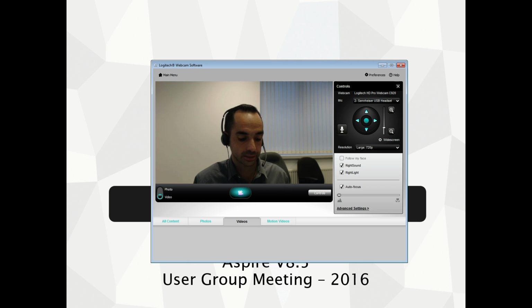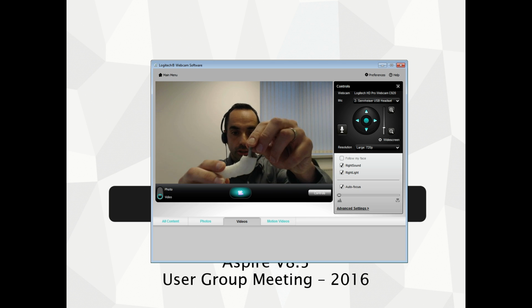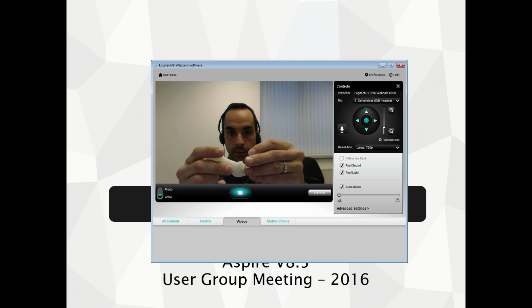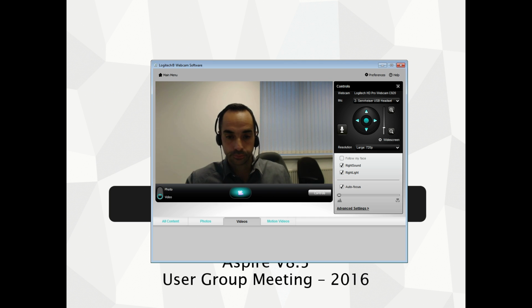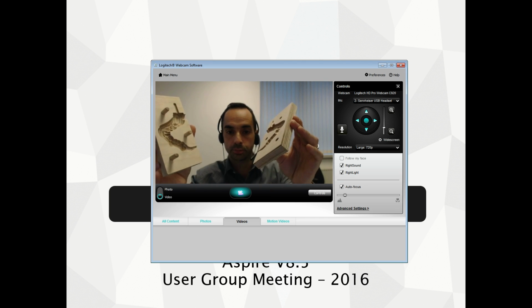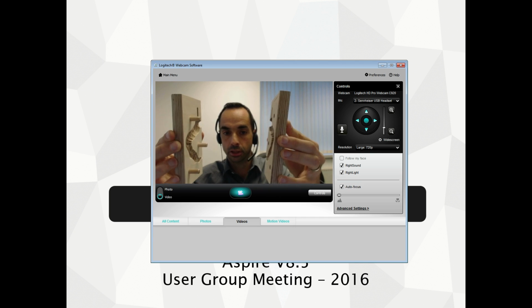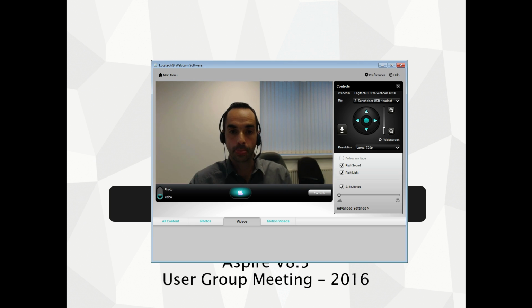The example we're going to look at today is a mould created out of plywood, which is going to allow us to mould this part you can see here. This is a dragon's claw, white plastic, and it's got a bolt embedded here in the top. Hopefully you can see that there, that we can put a nut onto. It's threaded, and that's embedded in the mould, and this is moulded from a two-piece plywood mould that looks like the part you can see here that I'm holding up, and this just goes together, and we put some melted material into this, which I'll talk about in a moment, and that allows us to form the claw with the bolt in it.